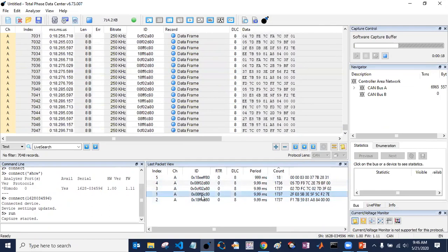Our particular custom message that we just defined in our source code, which is FF6C, is a PGN, and 80 is the source address that gets assigned dynamically based on the sensors that are connected on the CAN bus. It is 8 bytes of information, 64 bits, and it's coming at 100 Hertz, every 10 milliseconds. As you can see, all the data is in hex format. If you want to get this value in a decimal format so that it's readable, you can use a DBC file that we provide as well, which I will talk about in a later slide. So this is how you can confirm that you've successfully created a custom CAN message with the data packet rate and all the configuration.